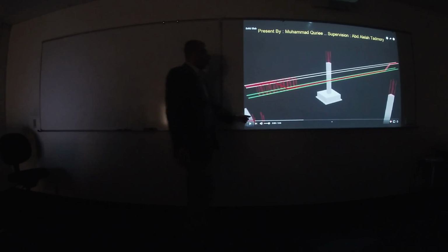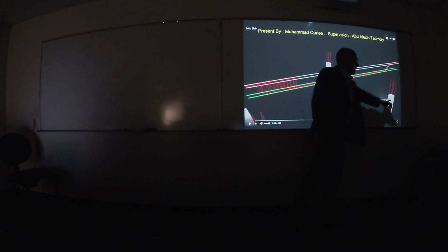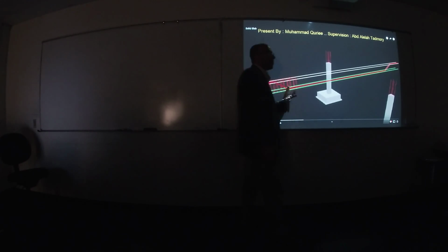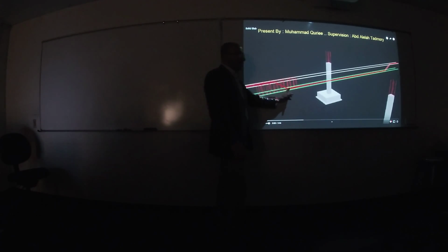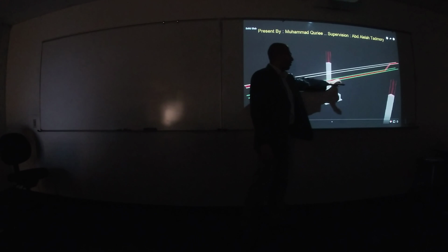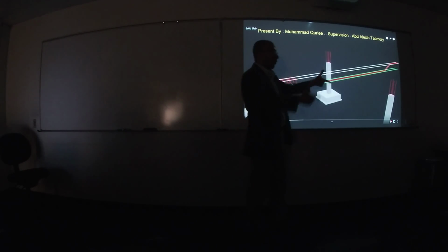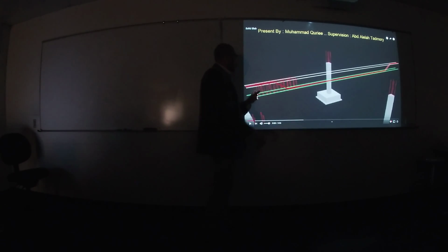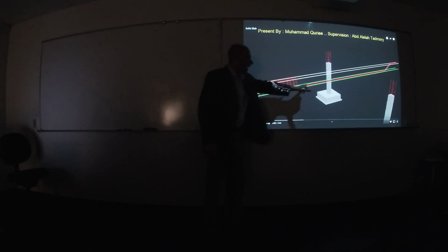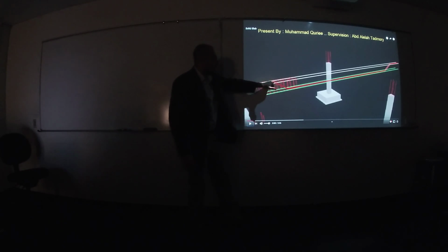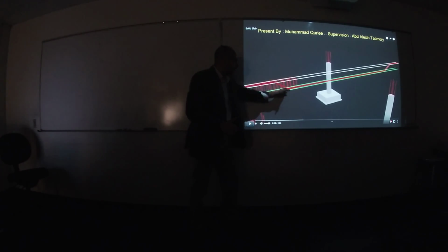We have a column. Between each column, we have a beam. In your beam, mainly, we have longitudinal bars for moment. We have stirrups for shear. Sometimes we can bend the longitudinal bars like this to support shear also. So this shape supports shear at this location.